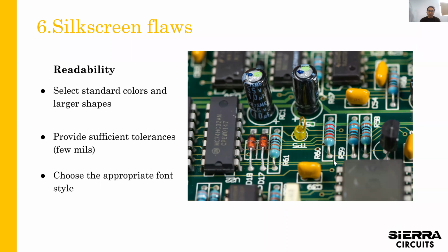And sometimes if you clip it too much, now the AOI machine in assembly can't read the silkscreen information. Maybe we lost the pin 1 marking, and maybe it's not clear what the location of that component is. So you have to be careful with properly aligning your silkscreen and following the manufacturing rules and the keep out for silkscreen.